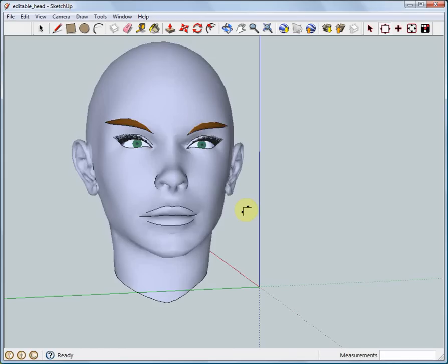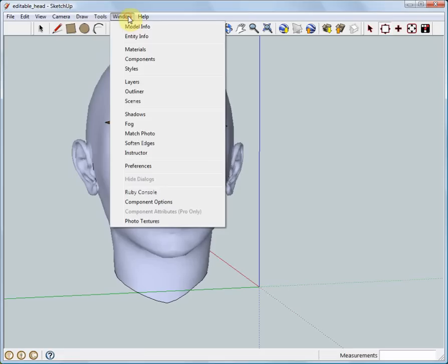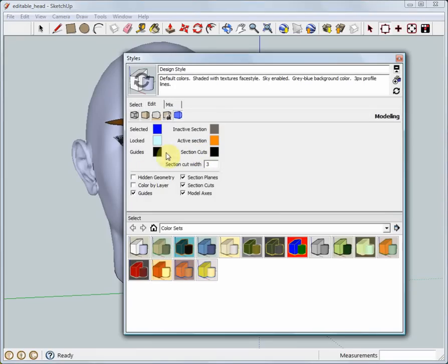In this example, we have a 3D drawing of a human head we have created by drawing control curves and weaving surface meshes within these control curves. We will reshape the model here by editing the control curves and smoothing the associated surfaces. For easy display, we place the control curves here in a different layer.